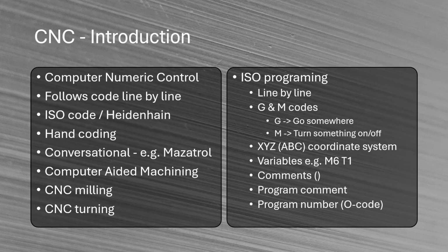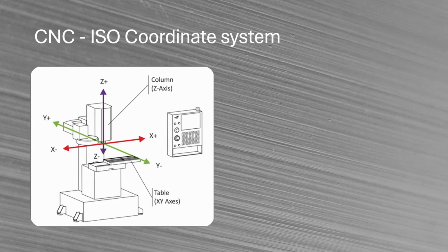Numbers under 1,000 are machine programs, is the way we do it. So user programs have to be 1,000 and over, but not over 9,000. So it's between 1,000 and 8,000, you could say. Other than that, it doesn't matter.